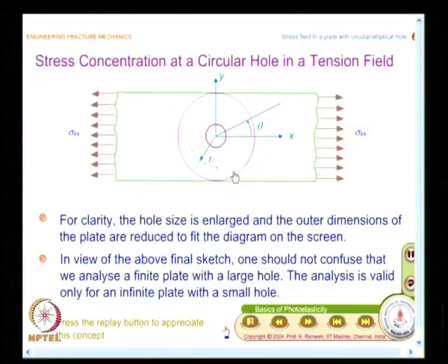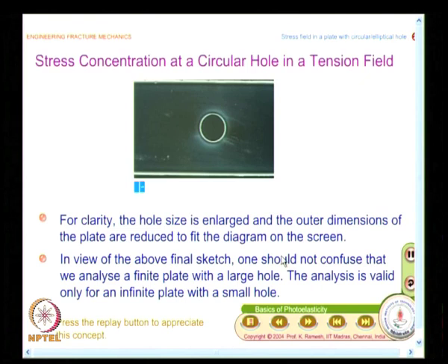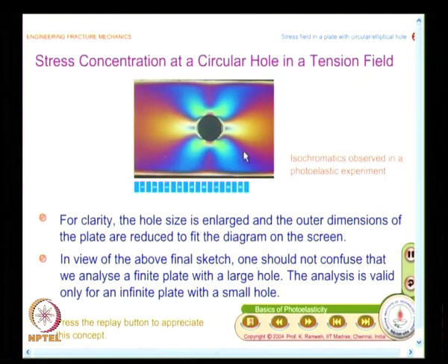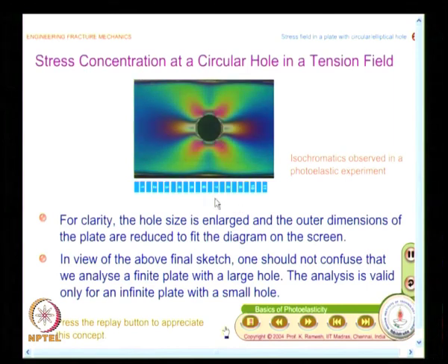And the polar coordinate system is a lot simpler. That is the reason an infinite plate with a circular hole was solved first. And we will also have a brief look at the principle of superposition employed, and before I get into that, you have a nice set of fringe patterns that are formed because of photoelasticity, and this is for a finite plate.